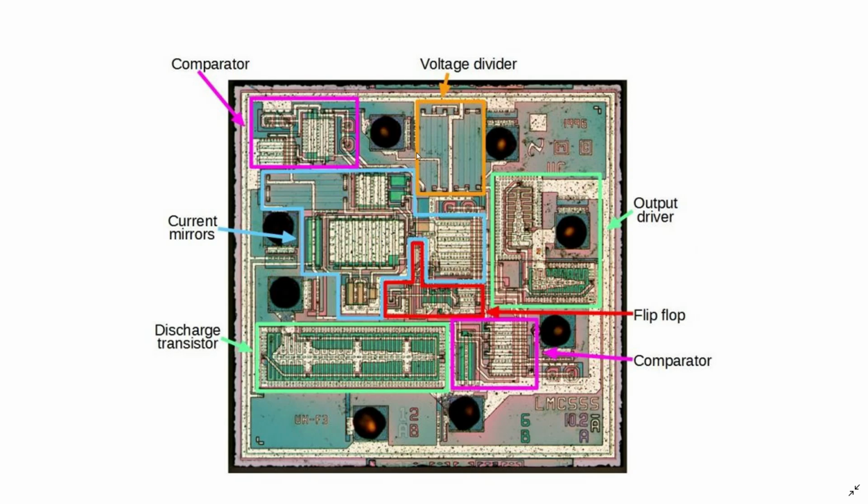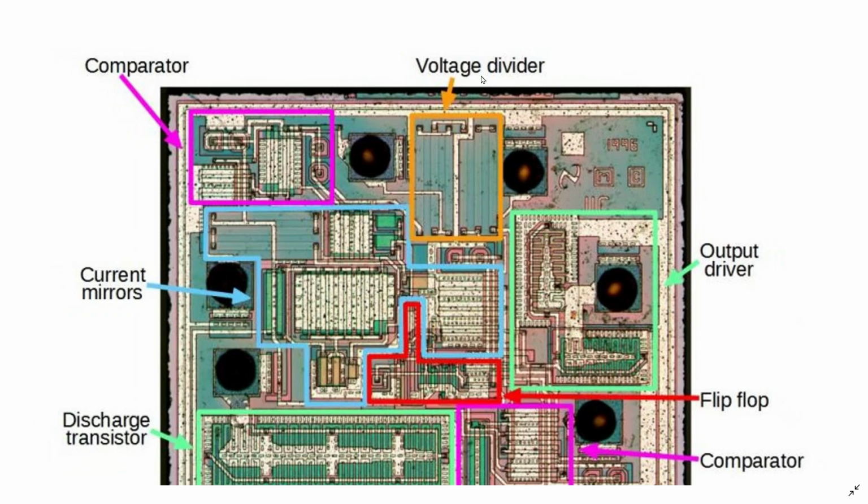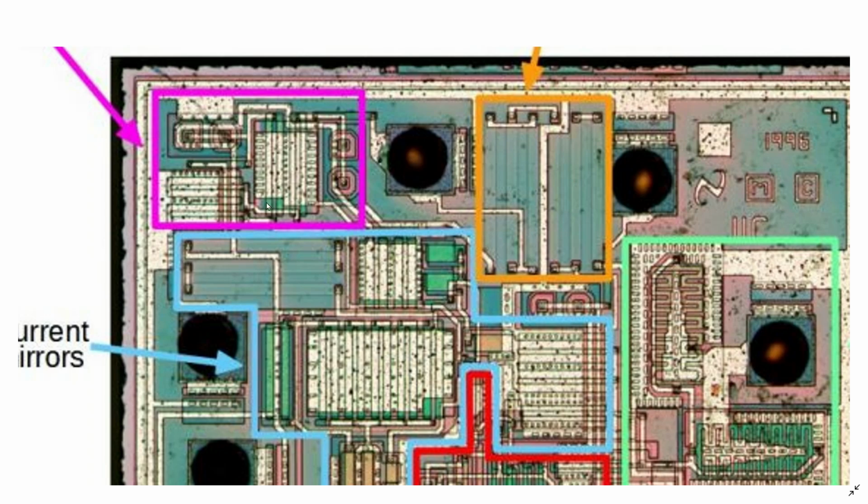So already we have discussed the block, the yellow color, the highlighted box. So this is our resistor divider. They have created 2.5 resistors, and then they have implemented an interdigitization based matching pattern here. So this is your voltage divider block, that is nothing but our resistor divider. And on the right hand side we have another block. So this block is a comparator block, okay.